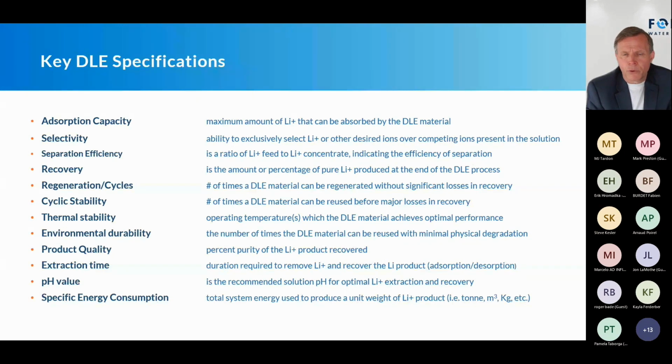An interesting point, in working with the DLE suppliers, is that when they tell you how many cycles, you really need to ask, how did you calculate those cycles? Is it real world? Not a lot of people have that data, but then how did you do that projection? And I will point out one thing you should look at on the cycles, because microcontaminants will slowly load up on the materials. So over time, performance will go down. The cycles may go down, but that happens over a couple of years.